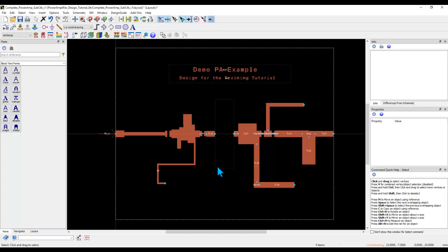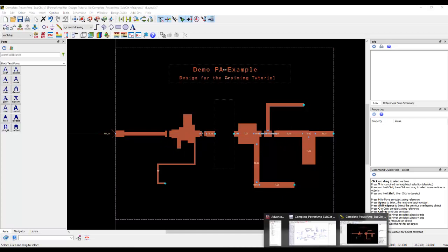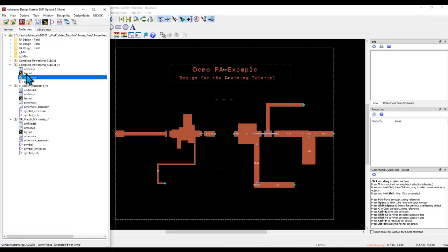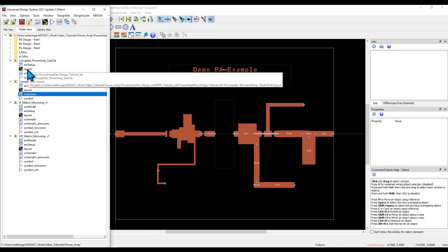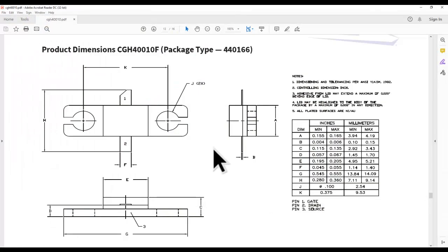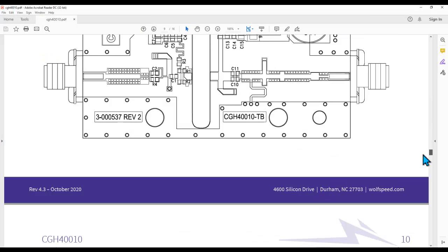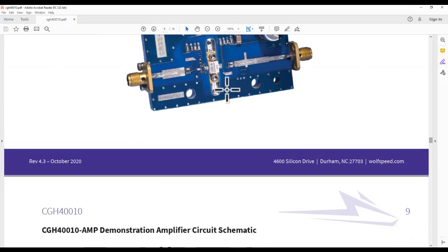But just before we go to plane, remember when we fabricate this kind of PCB, we might need to do some tuning, right? Because sometimes due to tolerance of components, due to the data sheet and model, nonlinear model difference of the transistor, our performance might shift a little bit, or even with the PCB tolerances, either fabrication or dielectric constant, etc. So we may need some flexibility to tune these kind of devices or circuits after production.